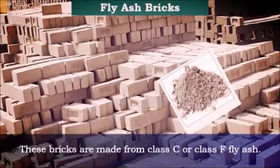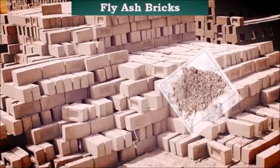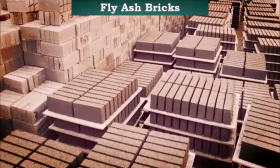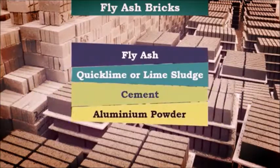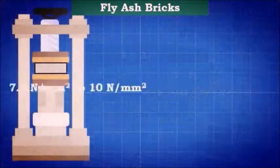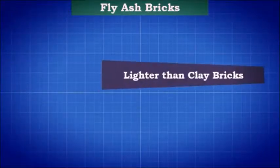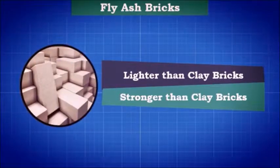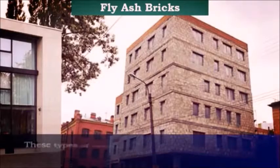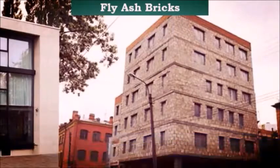Fly ash bricks. These bricks are made from Class C or Class F fly ash. The main ingredients of fly ash bricks include fly ash, quicklime or lime sludge, cement, aluminium powder, and gypsum. The compressive strength of fly ash brick is normally of the order of 7.5 Newton per millimeter square to 10 Newton per millimeter square. Fly ash bricks are lighter and stronger than clay bricks. These types of bricks are used in cost-effective and eco-friendly construction.